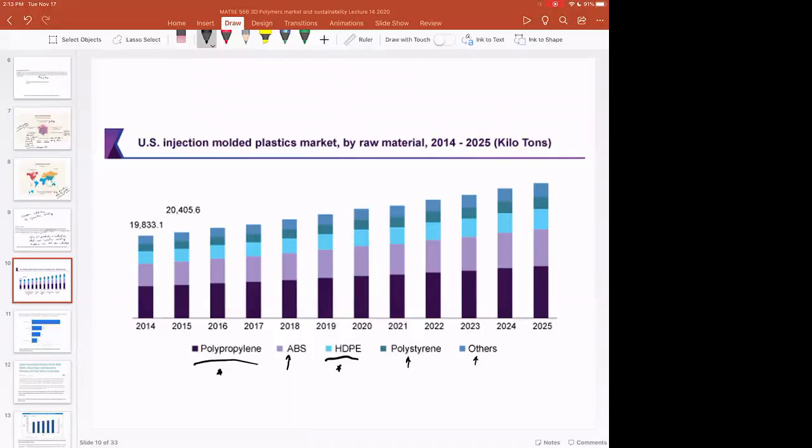And these two polymers are not additively manufactured a lot because the cost to do injection molding of these polymers is so low, and a lot of commodity components are made out of these polymers. So again, where's the opportunity in terms of mass, and then where's the opportunity in terms of value add for additive manufacturing?